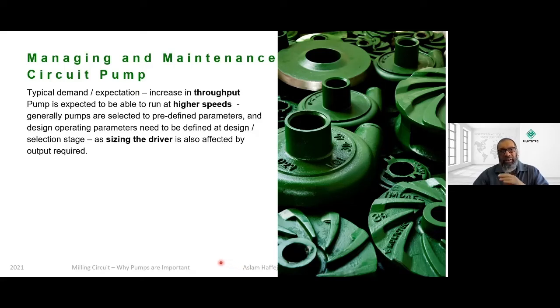pumps are designed and selected and sized to predefined parameters. So you give flow rates, densities, etc. at the outset of the selection of the pump, and that's what the pump supplier sizes the pump to do. And remember, it's got the sizing of the driver; it's got a particular kilowatt motor selected to do that job. Now you can't just go willy-nilly and try to speed up the pump, and then suddenly you find it's